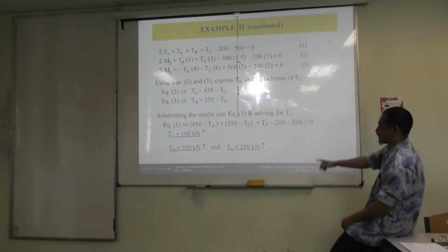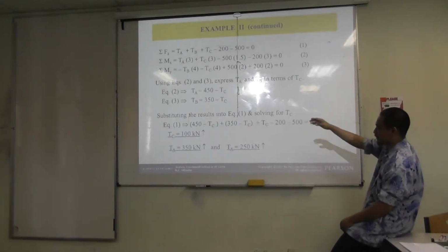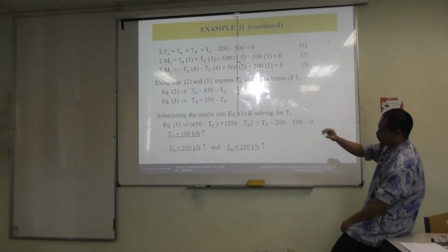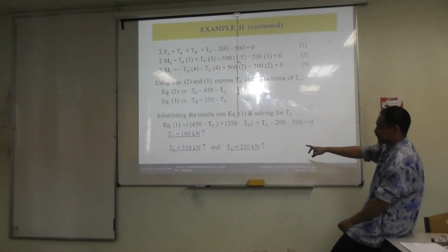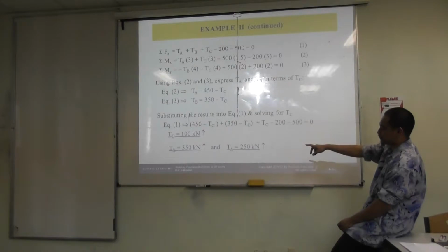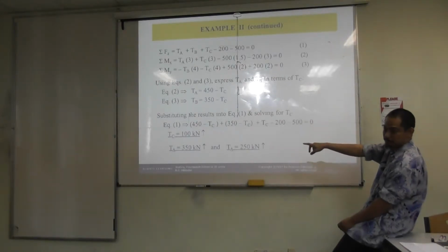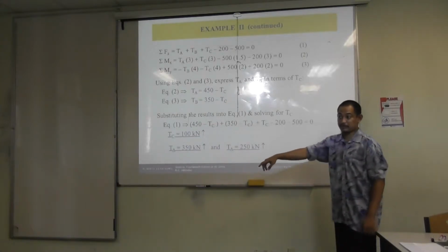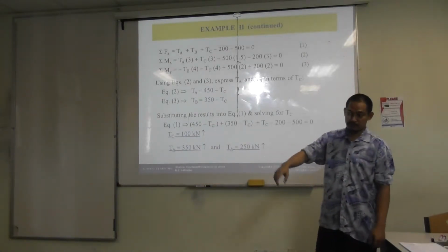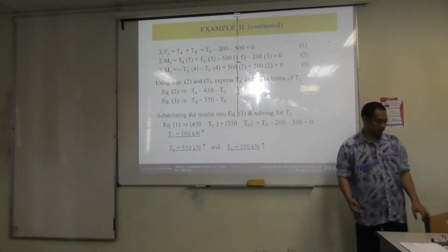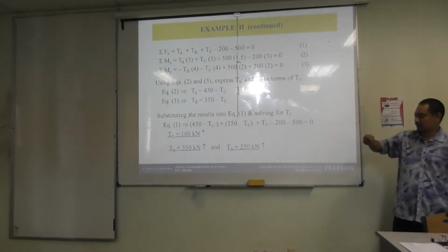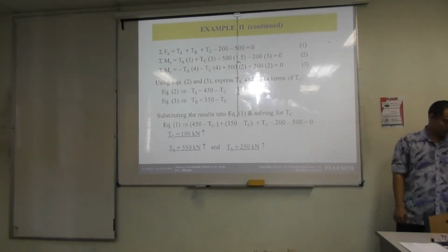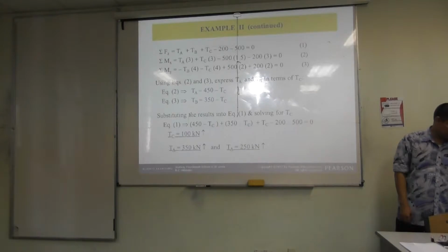Of course, in a question like this specific question, if you notice, everything is positive. So if you get a negative in any of the answers, it should be wrong, right? Why? Do you understand why? Okay. Yeah, because the question is all the tension is in the cable, right? There's no possibility of that becoming negative.